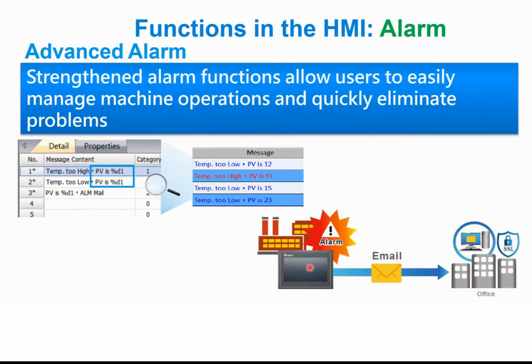On the HMI, you can display the alarm message and also attach the screen of the alarm in the email. So when you have a system that is very critical, you want to monitor what happens. This function could be handy for your machine. What you do in the HMI software is enable this function and the alarm will be ready.